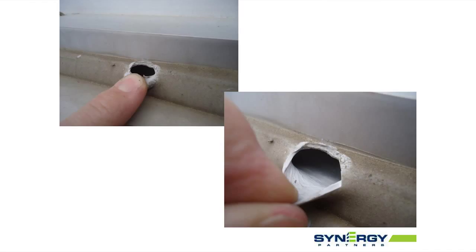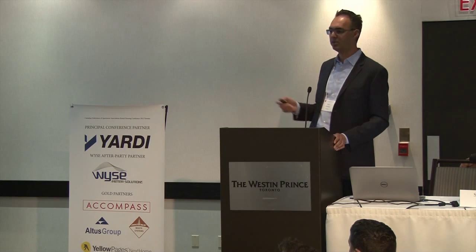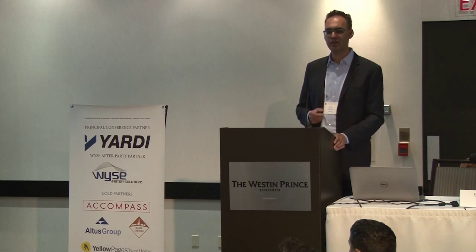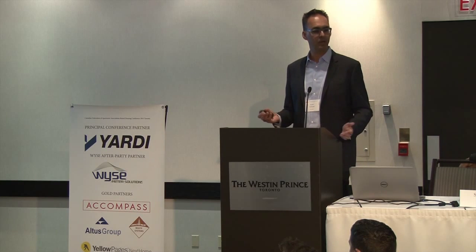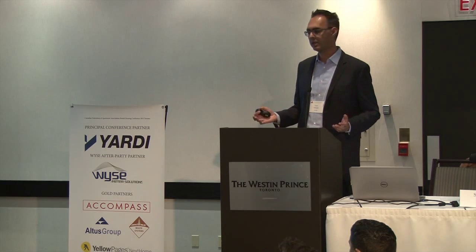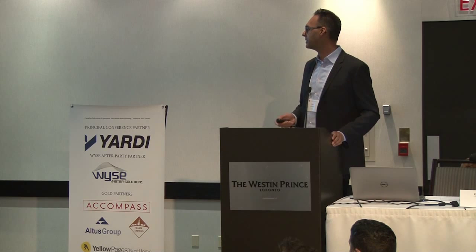And I've run across a number of buildings now where this is the case, and the sealant is just barely bonded onto the window frames by probably a millimeter or two. It's just very, very minimal. And so it's easy to walk past something like that. You look at the windows, it's a new installation, you think, wow, this is great. This looks really good.